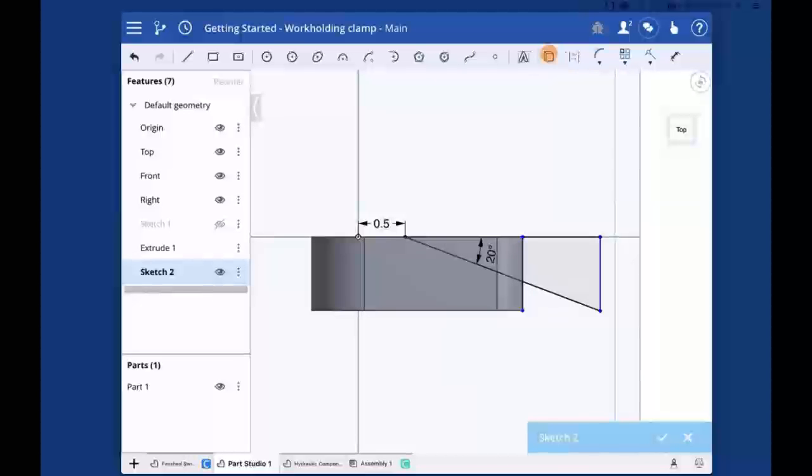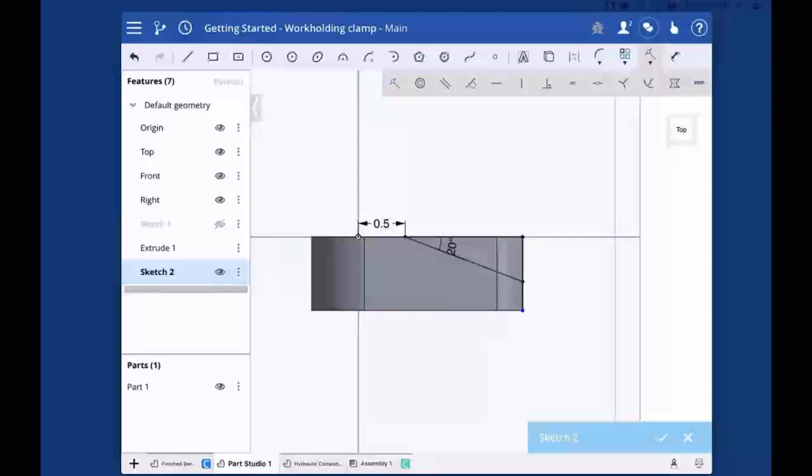The neat thing about that is now you can attach those two, and you have a triangle that's attached to the end of your part, the correct design intent. Just a tip, you have the use command. Again, the idea behind the Onshape apps is that they're full-fledged CAD editing tools and not just view tools or markup tools or something along those lines. So I've converted the edge. I attached my geometry to the edge. Now we're done. We're ready to create our cut.